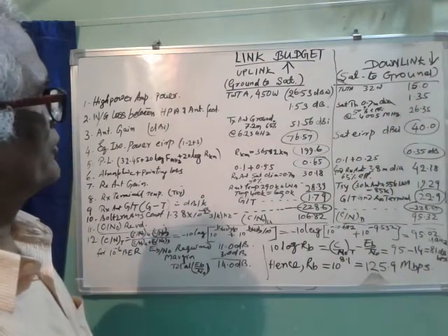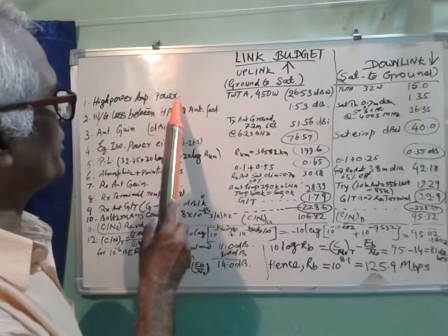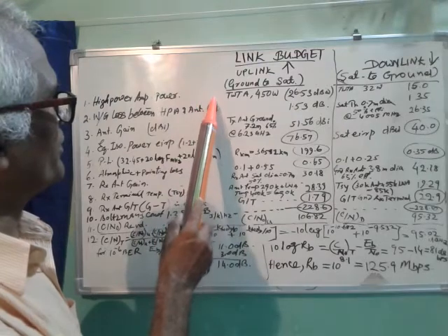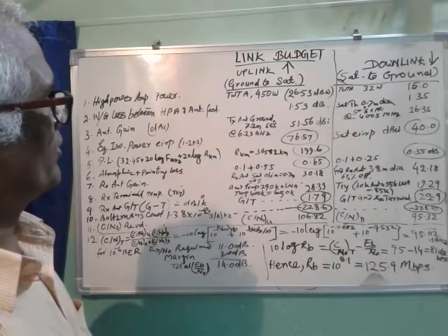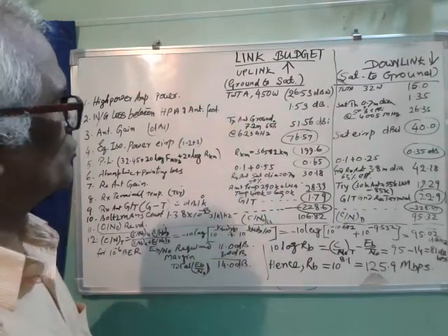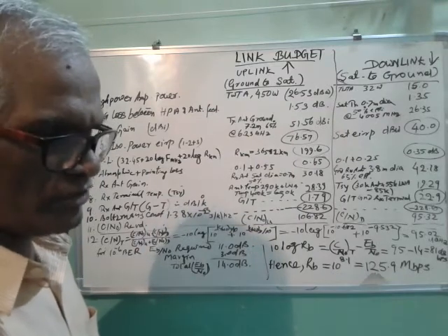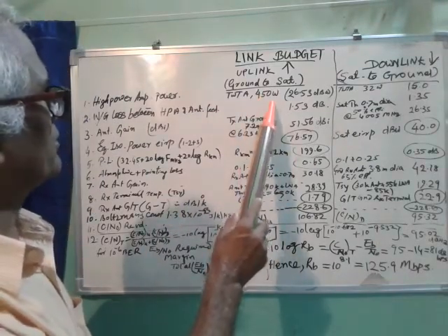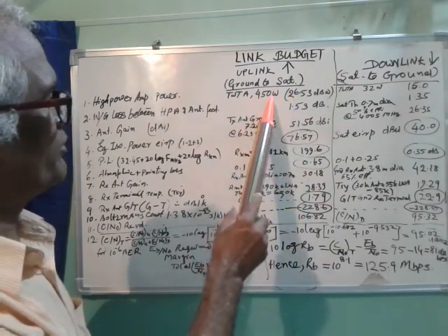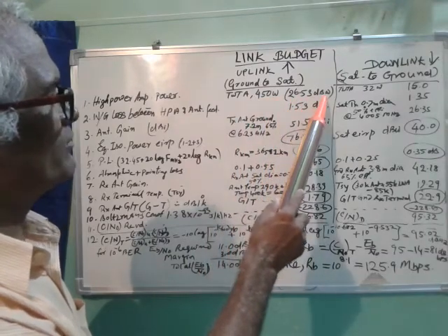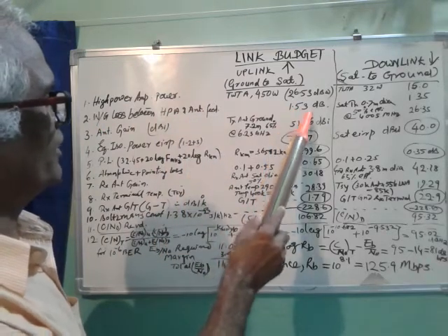Then we start with the high power amplifier, which will amplify the information. Generally in the amplifier stage, traveling wave tube amplifiers are used the most. SSPA is also used. Then high power Klystrons are used. Here for 450 watt, the ground station is using a TWTA, and 10 log 450 watt is equal to 26.53 dBW. And waveguide loss from HPA to antenna feed will be 1.53 dB.